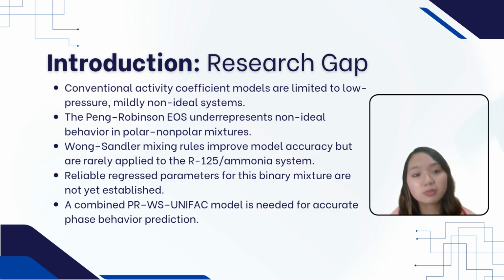in polar nonpolar mixtures. On the other hand, the Wong-Sandler mixing rule improves accuracy by integrating excess Gibbs energy models with PREOS. Yet its application to the R125 and ammonia system is limited, and validated parameter sets are scarce. Therefore, a robust computational framework combining PREOS, the Wong-Sandler mixing rule, and a unified activity coefficient model is needed to accurately predict the non-ideal vapor-liquid equilibria of this binary mixture.